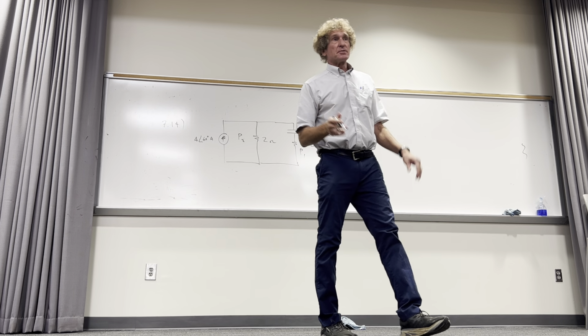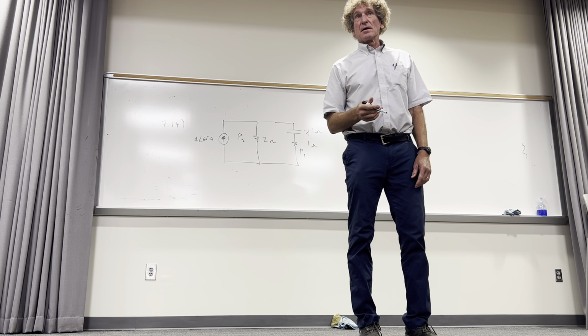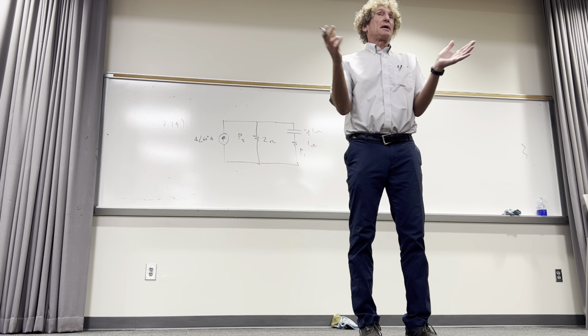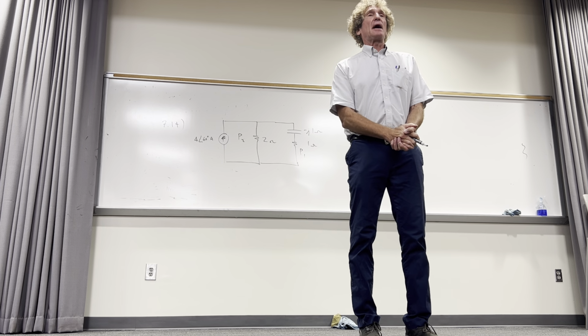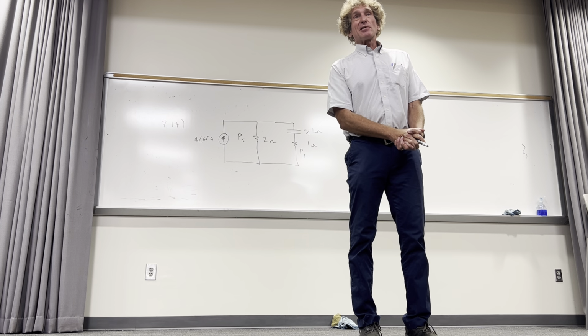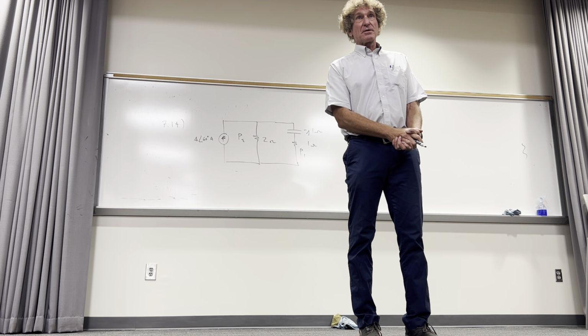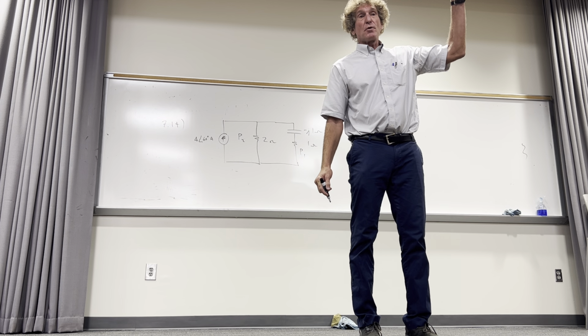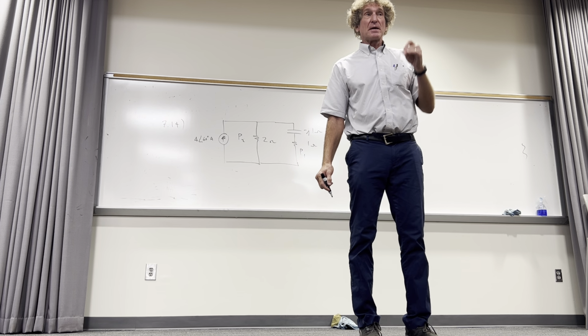A lot of ways to do this. There's no one best way. How would you try to do it? And what do we ultimately need to get the power based on what I told you? Well, we could get the voltage, but current is obvious, isn't it? Didn't I show you that 1/2 the magnitude of the current squared times the resistive part, if it's a complex impedance, just the real part of the impedance, is the power? How many remember that? Now, you're going to need to know this very well on Monday.